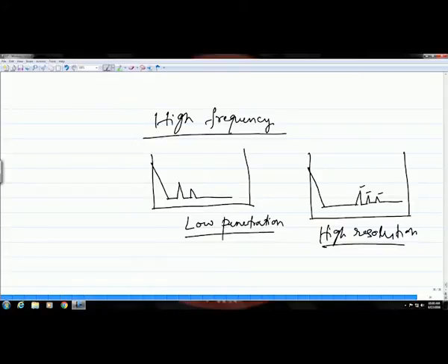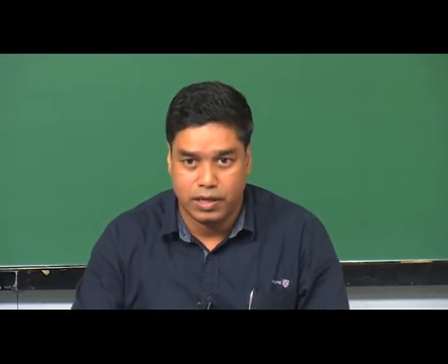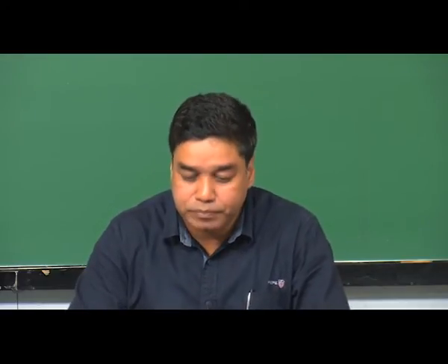So, that means this also tells you that when you want to do a closed surface analysis by ultrasonic testing, then you should go for high frequency, because as I said, in this case the penetration will be lower. So, your waves will be very close to the surface.